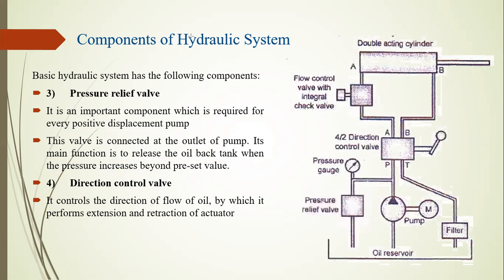Another component is a direction control valve. This portion is called a direction control valve. What is its function? It controls the direction of flow of oil, which performs the extension and retraction of the actuator.